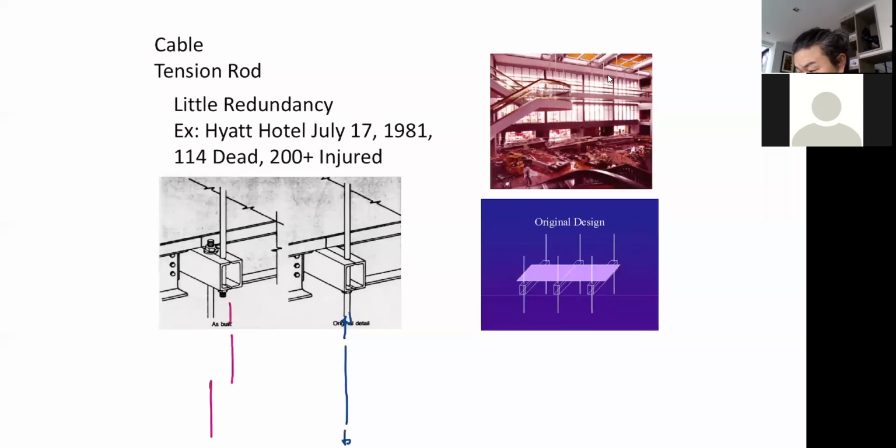So your tension is here and then there. But what about here? You see, the forces on both ends do not coincide anymore. So this portion cannot take the torsion that occurs because the two forces do not coincide, and it wasn't designed for it. So it got torn apart and collapsed.